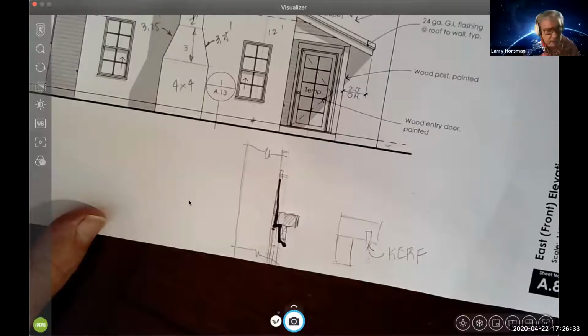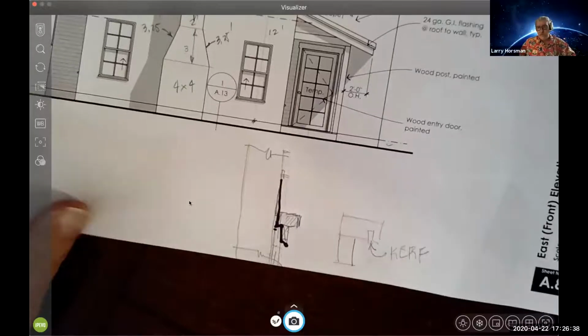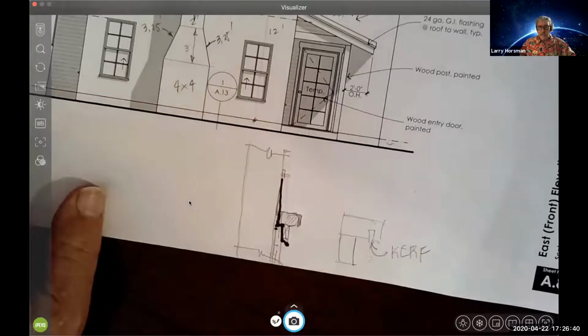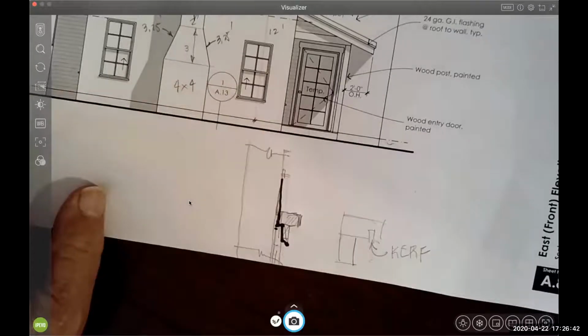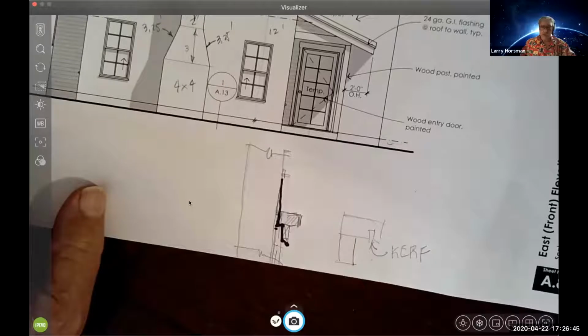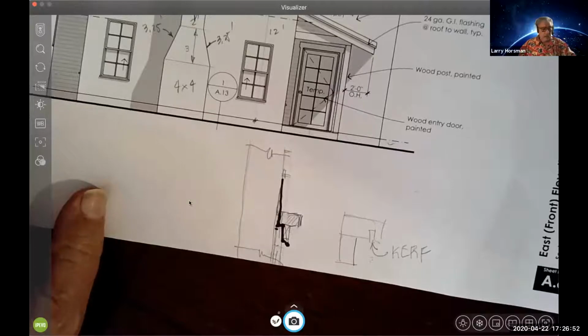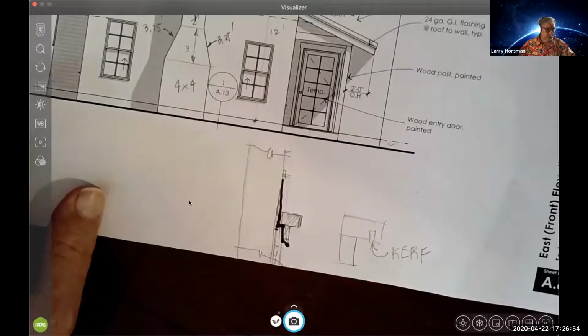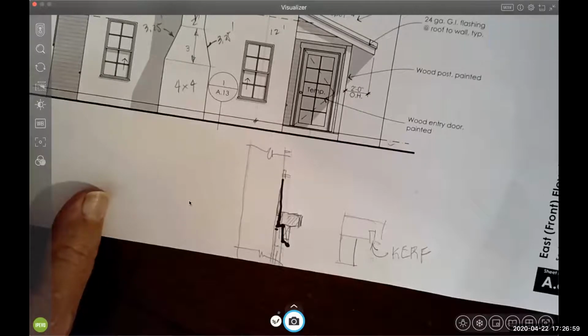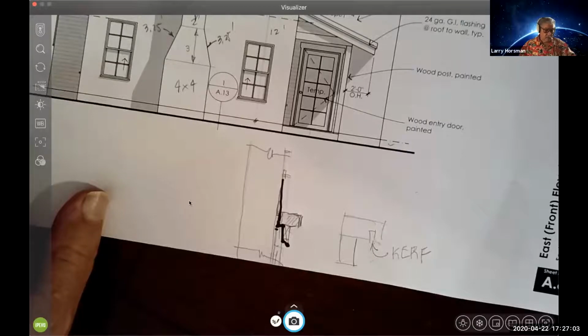The problem is that up until recently, plastic was usually more expensive than a metal flashing. Oh, okay. And the metal flashing will rust out, so it has a definite lifespan. So that's something else you would need to consider. Galvanized sheet metal, a lot of times, if you're using the very thin minimum building code 26 gauge, depending on the exposure, it may start rusting out somewhere between 5 and 15 years.